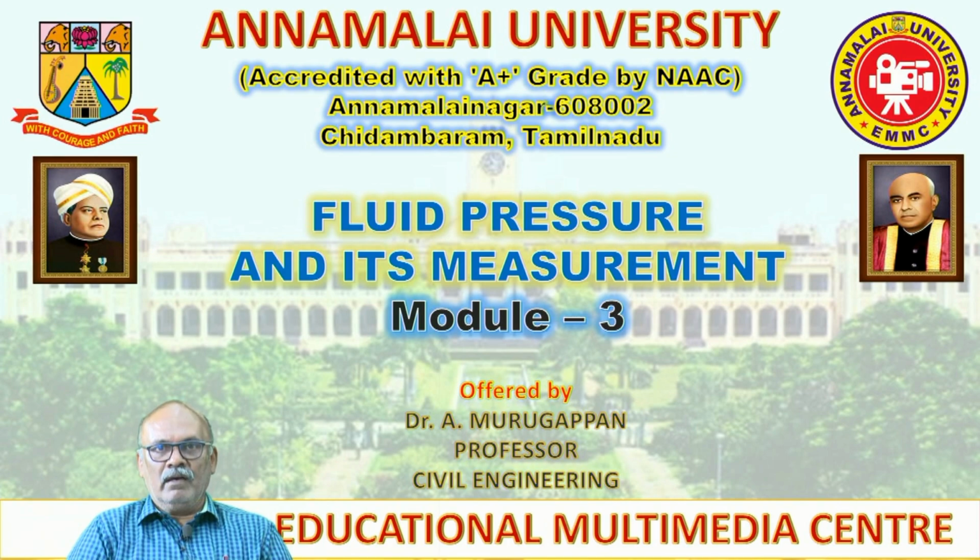So the convenient way of expressing the pressure at a point, in the majority of circumstances, is to take atmospheric pressure as the datum. And absolute pressure at any point is equal to atmospheric pressure plus or minus the gauge pressure. So use a positive sign if the gauge pressure is positive and a negative sign if the gauge pressure is negative.